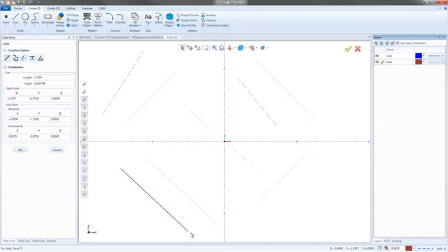And the big thing about this, it was something that I wouldn't do so much in the previous versions, because then it was a lot more switching colors. But now I can go in and I can set up all my layers before I start drawing anything. I could set up a specific color for each layer. The only problem I then have is I have to make sure to put my check mark on the correct layer when it's needed. So I need to make sure that if I was trying to draw dotted lines, the layer that I'm on has dotted lines set. So wherever the check mark is.